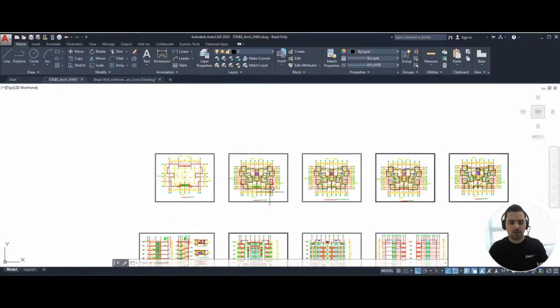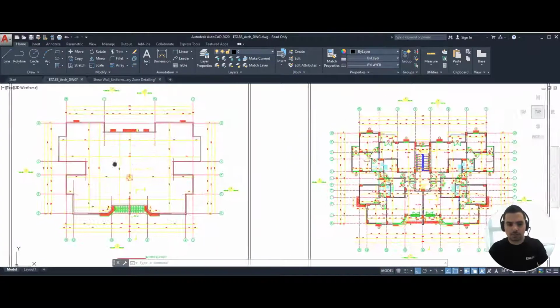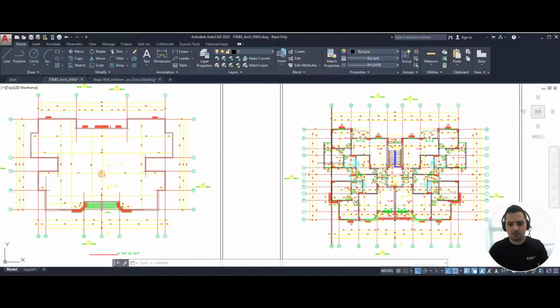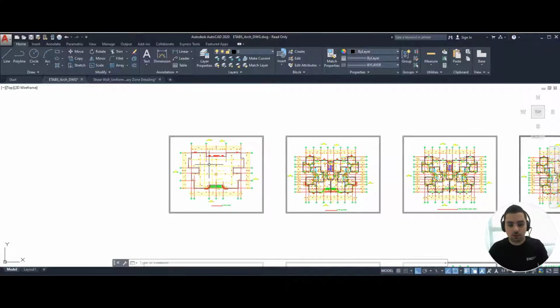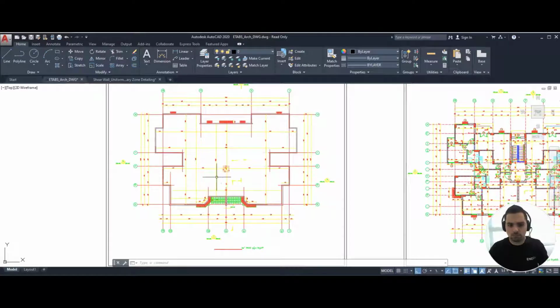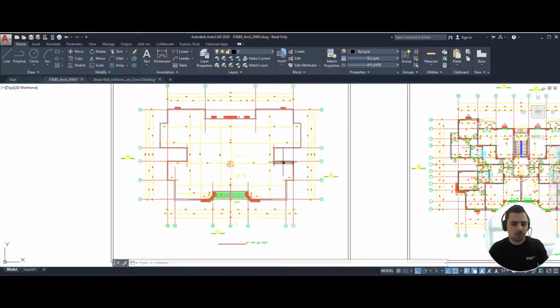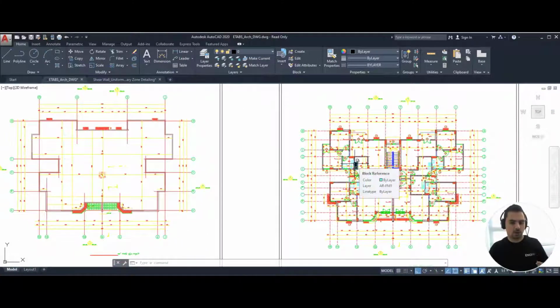Now, when it comes to other structural components such as slab limits and voids, these are floor dependent, so you do not have to move into the lower floor in order to draw them. You can draw them floor by floor. When it comes to your beams, we know that our beams are embedded within our partition walls. So in order to draw your beams, you also have to move to the floor beneath the floor you're working with.